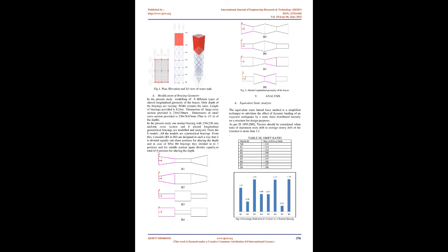B. Modal analysis. Modal analysis is used to determine the number of modes and corresponding mode shapes. Loads are applied as acceleration in X and Y direction. 12 number of modes are taken for analysis. At mode 12, mass participation ratio is approximately 100%. The effective mass participation factor represents the percentage of the system mass that participates in a particular mode. It provides a measure of the energy contained within each resonant mode. Type: eigenvector modal analysis. No of modes equals 17 at 99% mass participation.